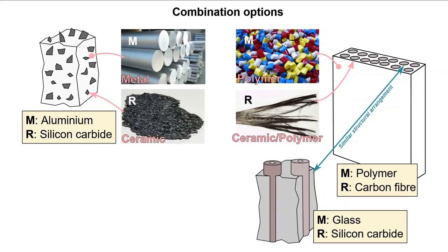The arrangement of the reinforcement in the matrix can operate on different length scales. While carbon fiber has diameters which are typically below 10 microns, silicon carbide monofilament is typically an order of magnitude greater than this. However, the arrangement can appear identical if the length scales are ignored.